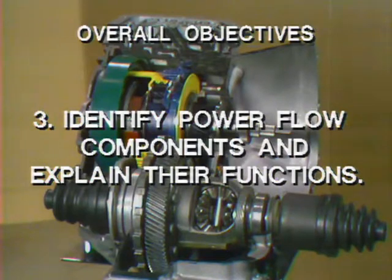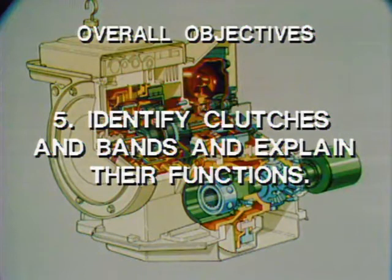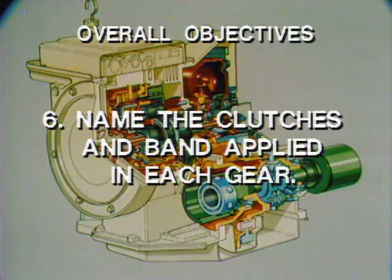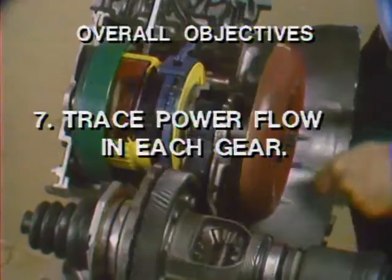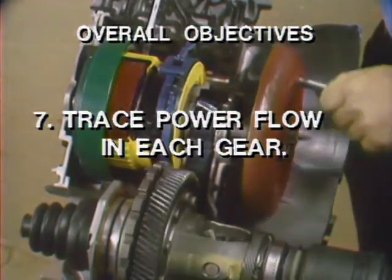function in power flow. 4. You should be able to describe the gear progression in each forward position of the shift selector. 5. Identify each of the clutches and bands that control the planetary gear train operation and explain the function of each. 6. Name the clutches and band applied in each gear. And 7. Trace power flow through the transaxle in each gear.